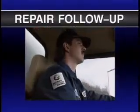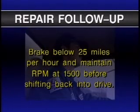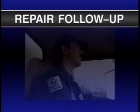Then perform the coast test again, remembering to brake to below 25 miles an hour and maintain RPM at approximately 1500 before shifting back into drive. You should find that the vibration has been eliminated.